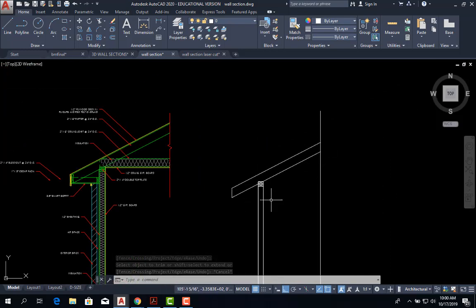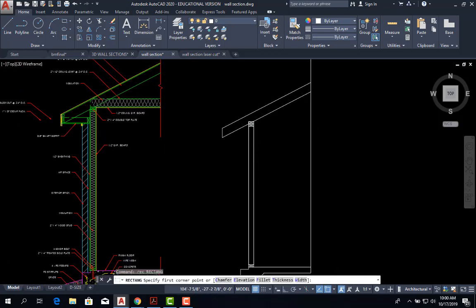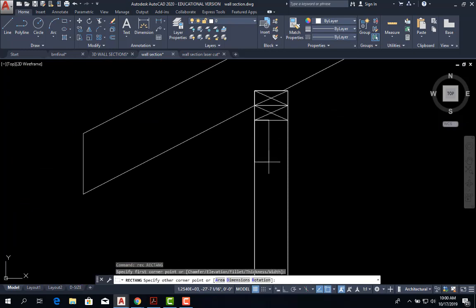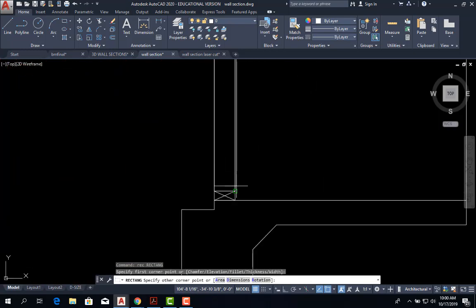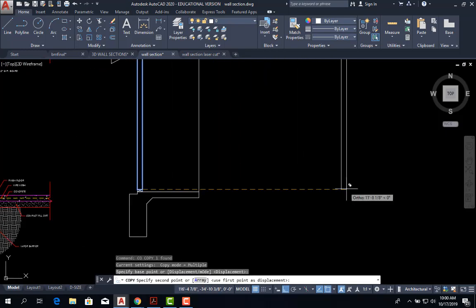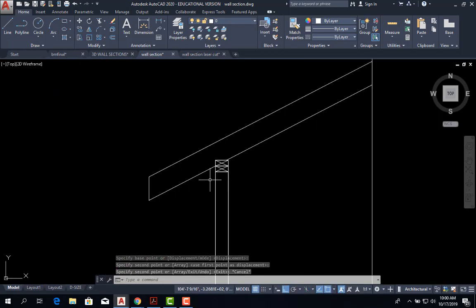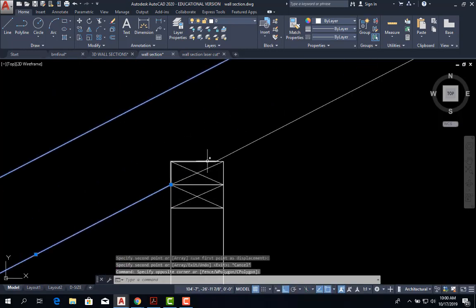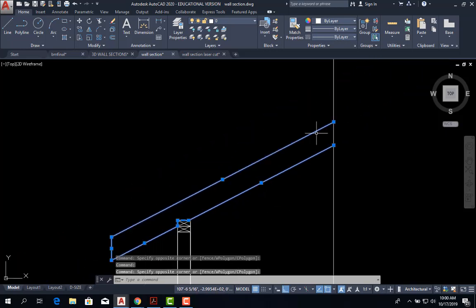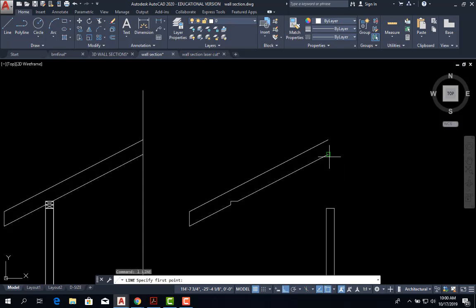Now I'm going to copy this again. You can do this, watch. Once you have this drawn, you can get this section here, and this is going to be your stud. That way when you cut it, you know where it is. And then I'm going to grab this right here, and I'll close it over here. This is going to be your rafter. You're drawing it so that when you cut it, it's exactly the size. So that's your rafter right there. You know exactly where it's going to cut, so it sits.